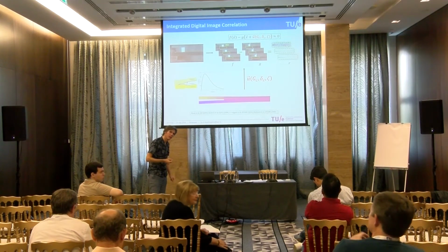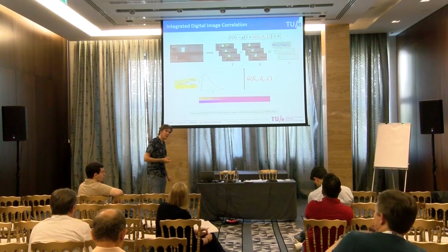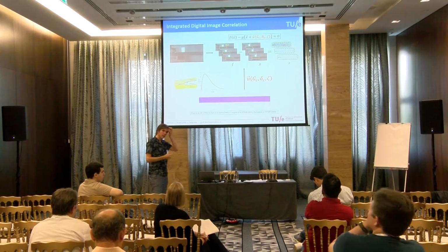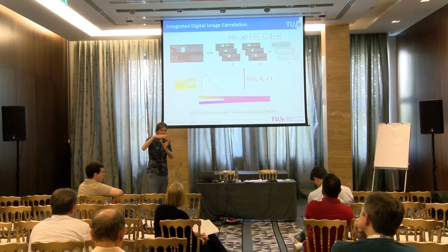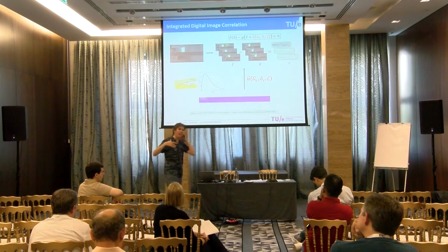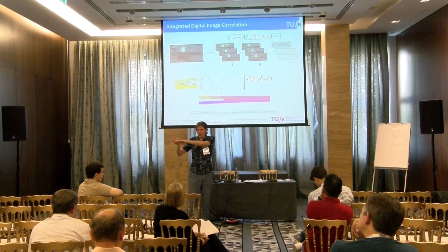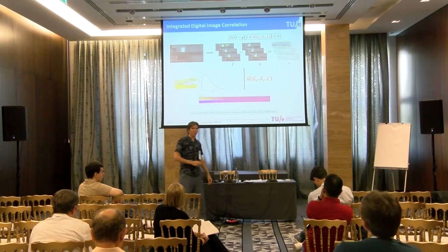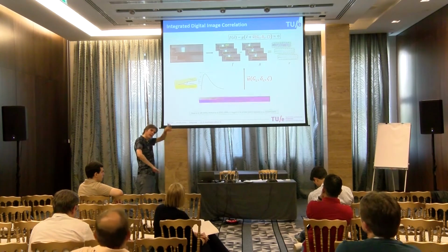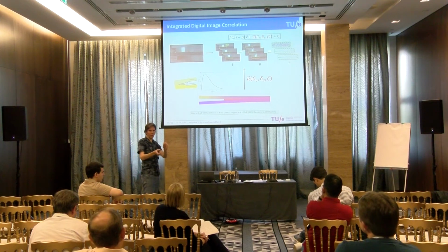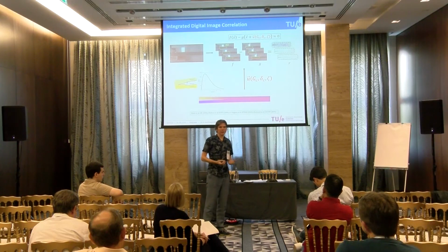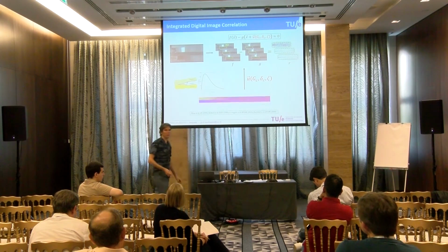So this would be okay for something with a really large process zone, like an adhesive? Yes, that's basically the case we're looking at. We have positive identification also for the 0.7 case, where the crack is just developing and we look at only a portion of it. But it's not optimal, because you would like to have all of the different mode mixities in your field of view, so all of the information, in order to get good sensitivity to the mixed mode ratio.